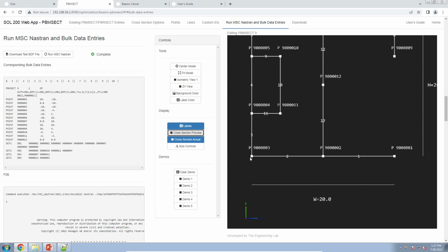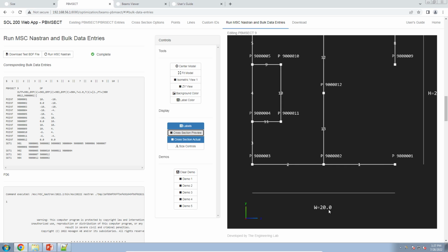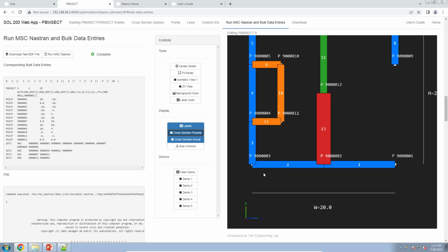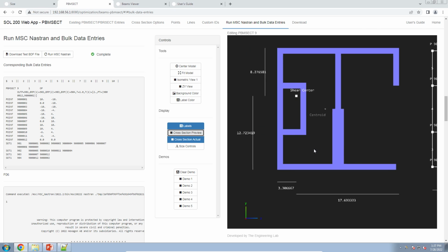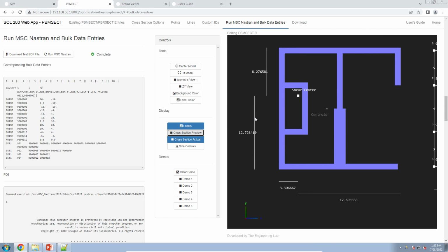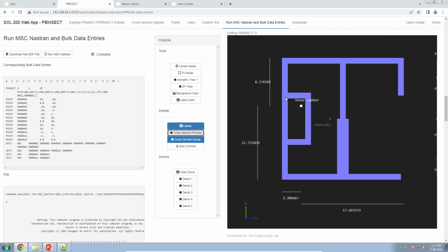So here we go from this left-handmost point to this right-handmost point that you see here on the screen. These width and height are not from thickness to thickness. It's from point to point. But these shear center distance lines, these are from the outer fibers to the shear center. So that is the second cross section.